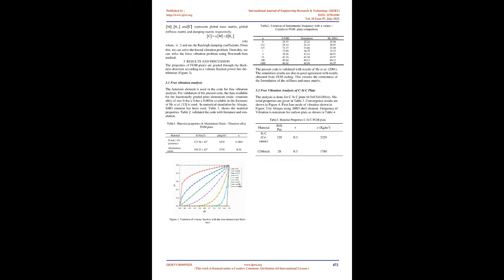2.3 Resultant forces and moments. The analysis of the FG plate is carried out to establish the relation between the forces and strains by considering transverse shear terms, where the vector represents the in-plane stress resultants, N, out-of-plane bending moments, M, and shear resultants, Q. Here, C is the constitutive matrix (9) of the FGM plate. To compensate for the parabolic shear stress variation across the thickness of the plate, a correction factor of 5/6 is used in the shear coupling components of the constitutive matrix (10).